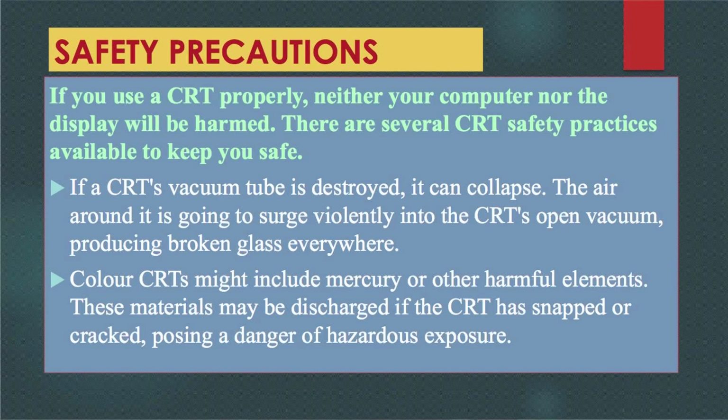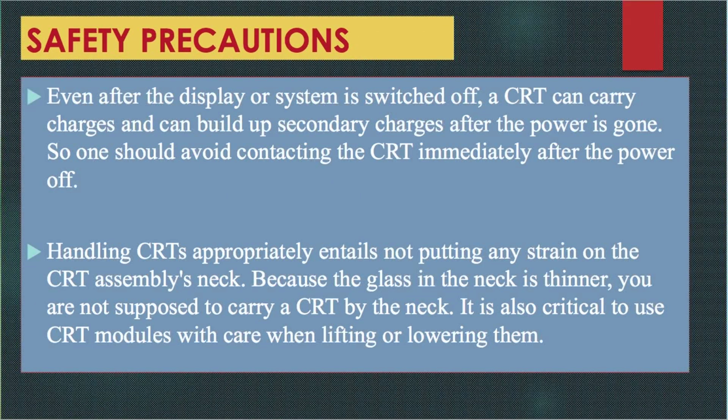Secondly, color CRTs might include mercury or other harmful elements. So these materials may be discharged if the CRT has snapped or cracked, posing a danger of hazardous exposure. Next point, even after the display or system is switched off, a CRT can carry charges and can build up secondary charges after the power has gone. So one should avoid contacting the CRT immediately after the power is switched off.